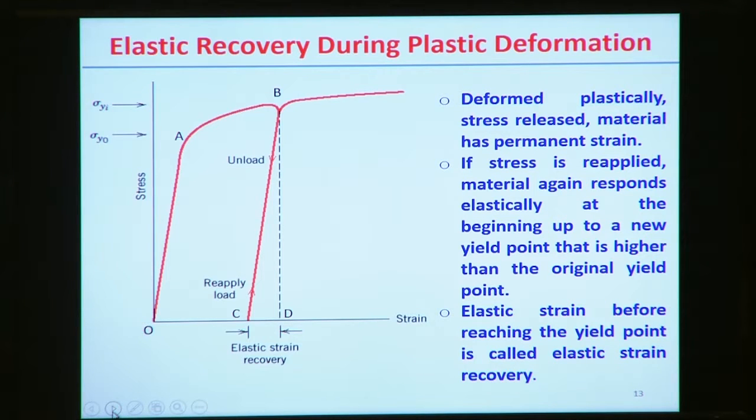Now, if a situation like that arises, if we try to deform the material, or uniaxial deformation of a specific material, up to a certain point, say point A, it follows an elastic deformation. Beyond that, if you see the nonlinear shape of the curve, up to point B there is a nonlinear deformation, and that deformation actually enters the plastic deformation zone.